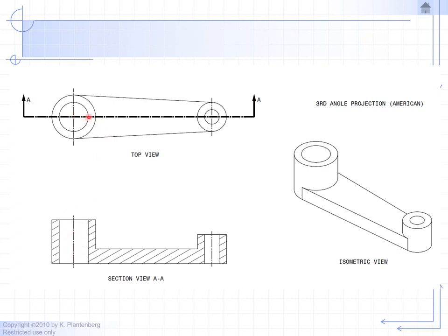And as you go beyond the hole, once again, the teeth of the blade are making contact with solid, cutting through the solid, leaving teeth marks. Okay, so we hatch that area. And then we encounter the smaller shaft. And as you cut through the shaft, you're cutting through material until you encounter the small hole. This is open space, so you do not hatch that area. And finally, you go through the last part of the solid, and you also hatch that area.